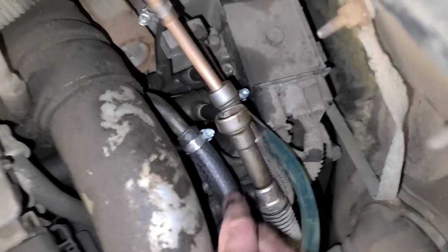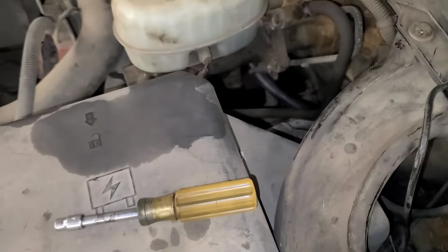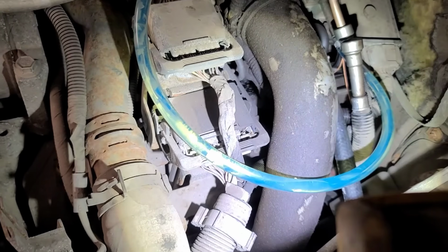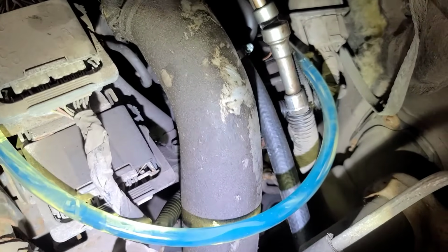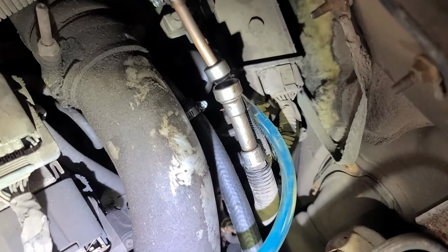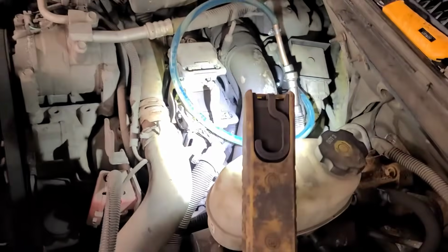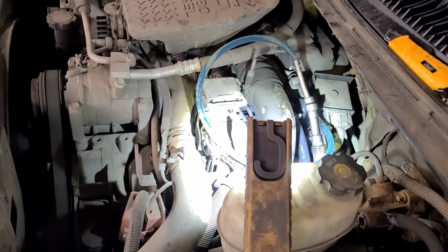You can see a new hose. I routed it. I'm going to tie it up here. Tied it along the frame. Connected it to the elbow coming out of the tank. So after about 15 minutes of running, you can see there's no air bubbles in the return line. So I'm going to connect the return line up as it was before. And we'll take a full road test. It does need number 8 glow plug replaced, so we'll do that at a later time.